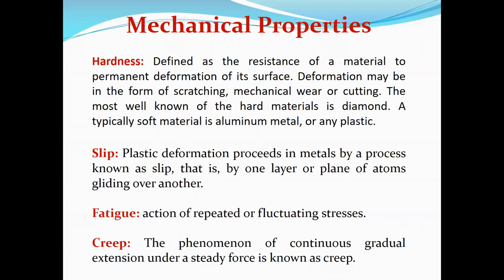Then slip. Slip means the plastic deformation which happens in a material. If you break down the materials, at one stage you will find atoms, isn't it? So atoms are arranged in various layers or planes. When, due to the application of load, one layer or plane of atoms glides or shifts to another one or shifts away, that is called slip.